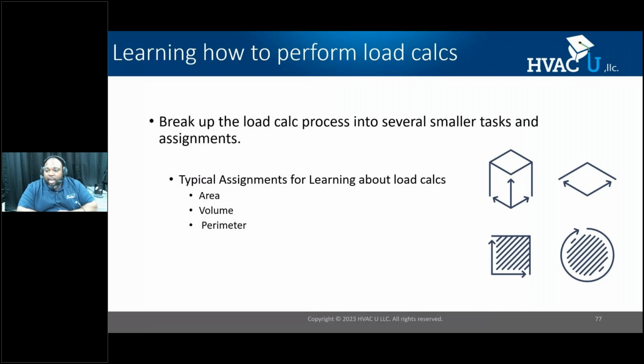All right. Now, load calculations could be a difficult topic for technicians to learn or grasp. And when I train and consult other organizations, one of the things I have them do is to break up the load calc process into smaller assignments. If you're an instructor, maybe having your technicians practice gathering information like the area, like volume, like perimeter. Basically, if they can measure and evaluate the proper inputs, whatever software they use, they'll always get good outputs.